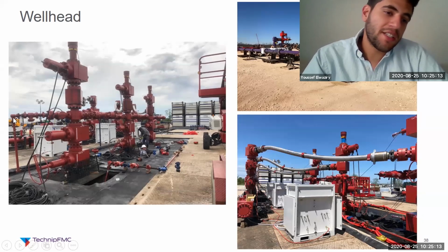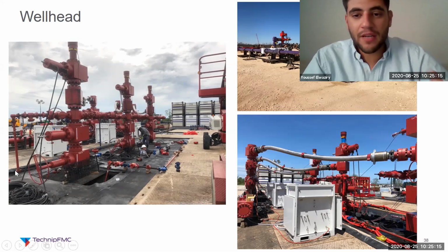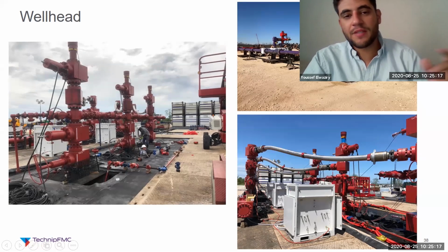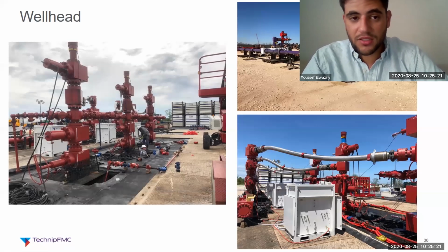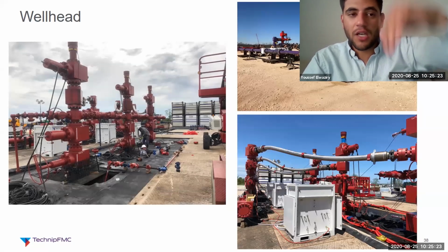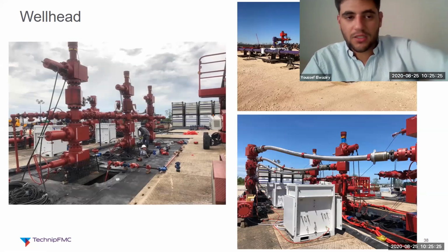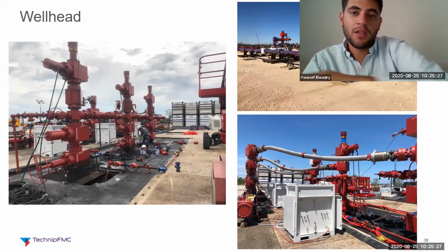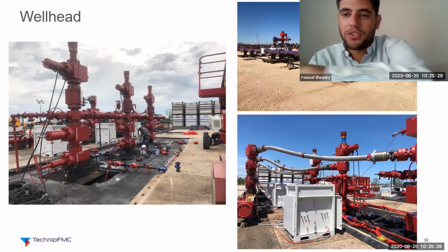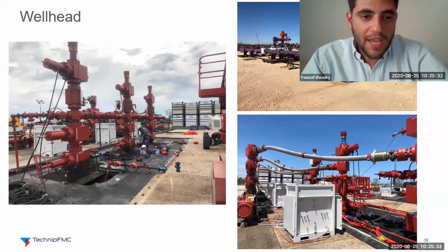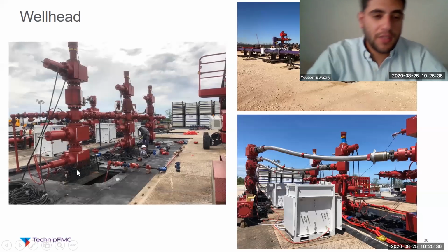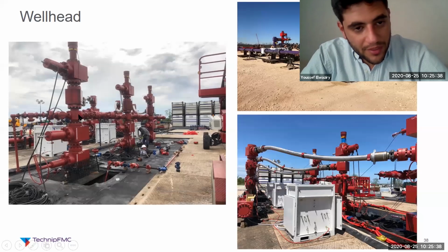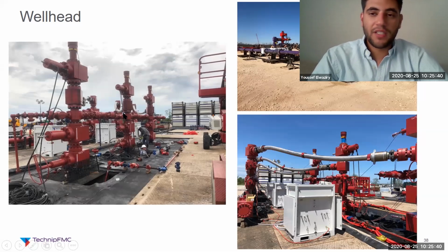Wing valves, one side is usually for pump down. Pump down, we'll talk about this later, is what we use to pump down the wireline guns. So whenever the wireline guns get lowered in a horizontal well, pump down is basically what pushes it to where it's supposed to be. And flowback. Flowback is basically if we need to flow back the well, then fluid is going to be coming here and then going to the flowback wings.